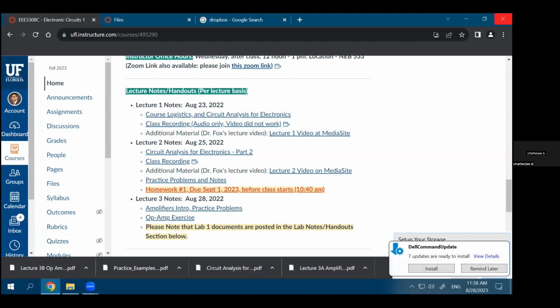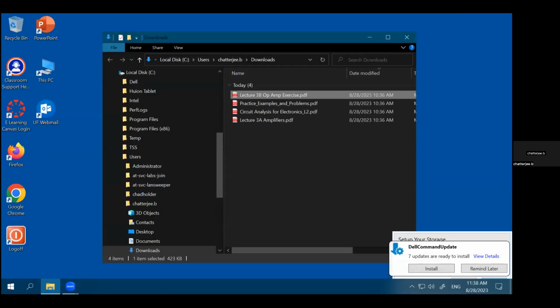So RMS voltage is actually one way to represent the AC swing. Maybe I can draw something on the board. This is the AC that we are talking about. And now you expect an amplified AC, right? That's the amplified one. What you talk about is the RMS, which is a way to represent the swing of this AC. If it is a larger swing, your RMS voltage will be higher, which is 0.707 times the peak. So you can represent this as RMS or peak to peak, whatever way you want.